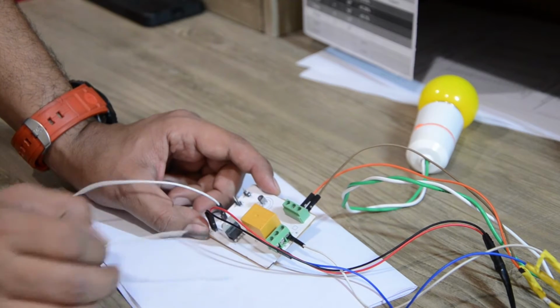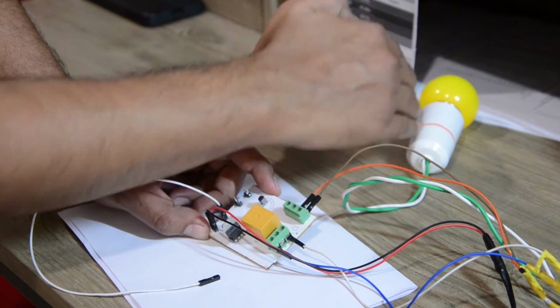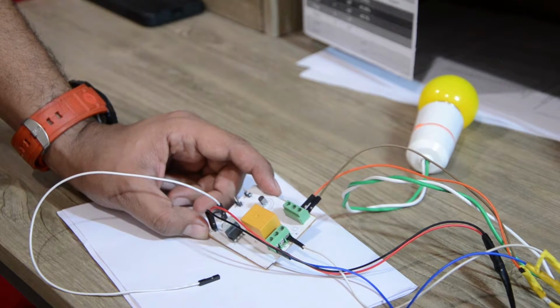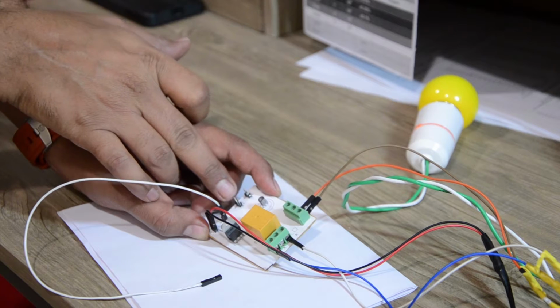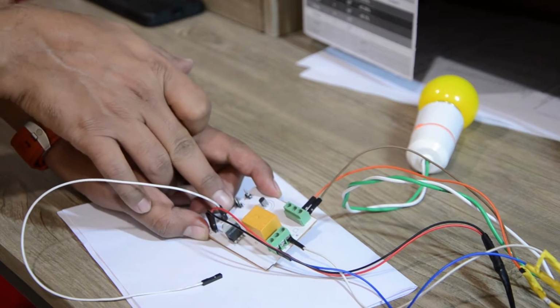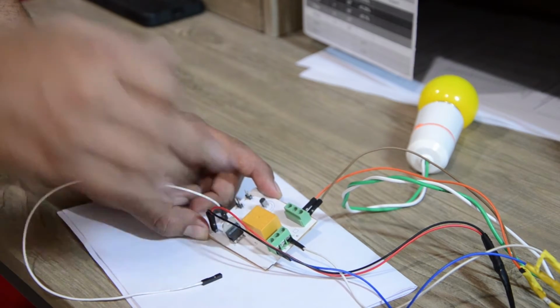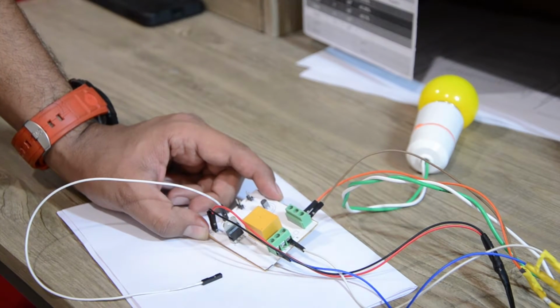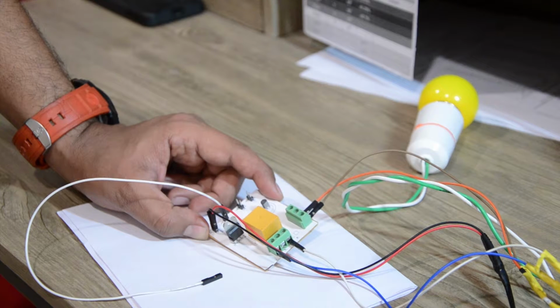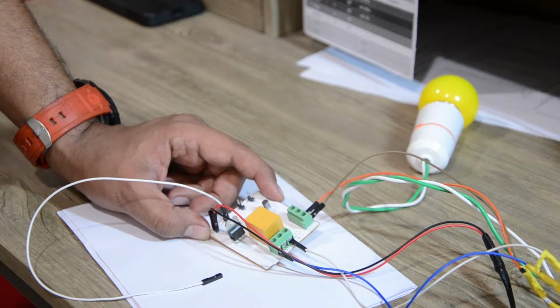So the relay board helps us in controlling the electrical appliances using just a 5-volt controlling signal. In this case, the relay board also provides us with the power supplies for the sensors and provides us a pretty safe environment to connect to our 220 volt AC from the wall sockets. Let's now look at the detailed circuit for the working of a relay board.